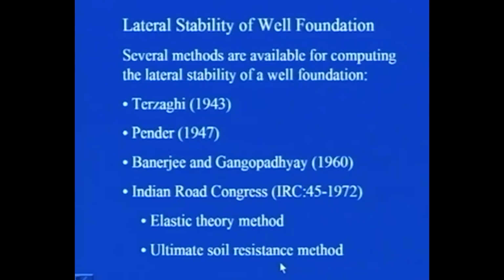So, using this IRC method, we have to employ these two methods, that is elastic theory method as well as ultimate soil resistance method, to get the lateral stability of well foundation.